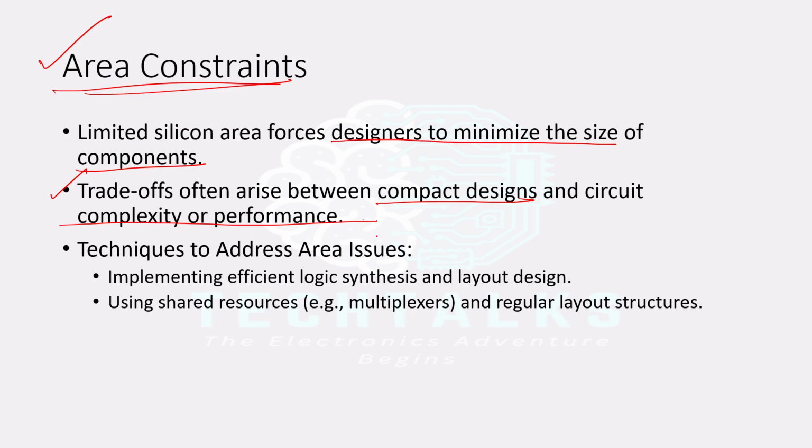Coming to techniques to address these issues, first is implementing efficient logic synthesis and layout design. What this means is, when you are designing a digital system, prior to the design of the system, we'll be writing RTL code and then verifying it, and after that RTL synthesis is done and layout design proceeds. While doing that, we have to make sure that we are implementing efficient logic.